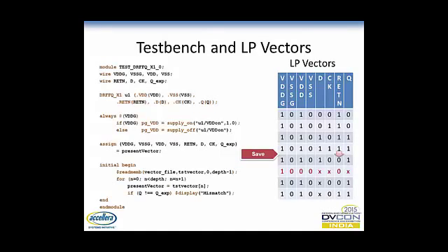As you can see here, first of all, retention is going from 1 to 0, so you're going into the retain mode, and then we are doing a power off, and then a power on, and then we are doing a restore. And for all these vectors, the last column shows the expected value, which is compared with the simulated value. If that doesn't match, it shows that the simulation is not working as expected.